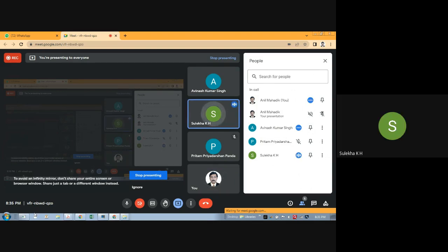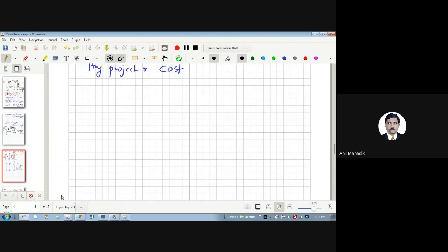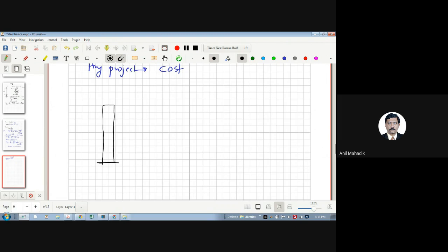Sir, in concrete sections also, the concept is same, no? Like if we have 4.5 meter or 5 meter floor to floor height. Same. See, you will learn that in the RCC part. Whenever we design any column, we learned last time only the axial force member column, because we were only looking at the conceptual part. But when there is compression, there is a slenderness ratio in compression also.